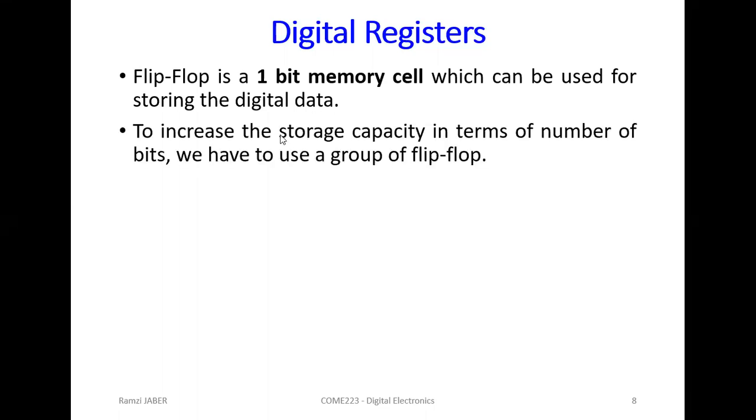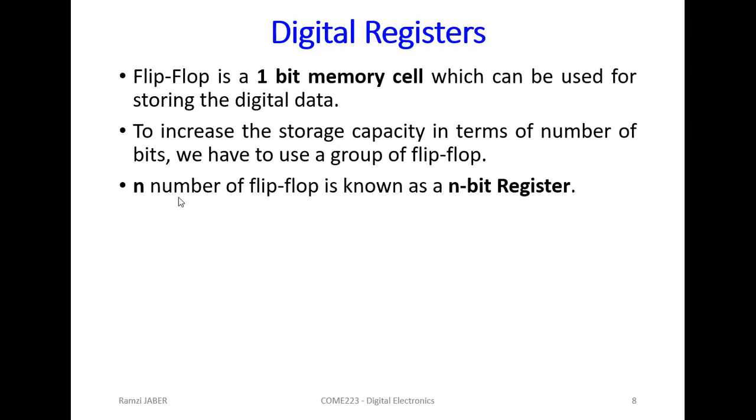To increase the storage capacity in terms of number of bits, we have to use a group of flip-flops. So one flip-flop, 1-bit memory cell. I want n bits, so I will use n flip-flops. Okay? N number of flip-flops is known as an n-bit register.